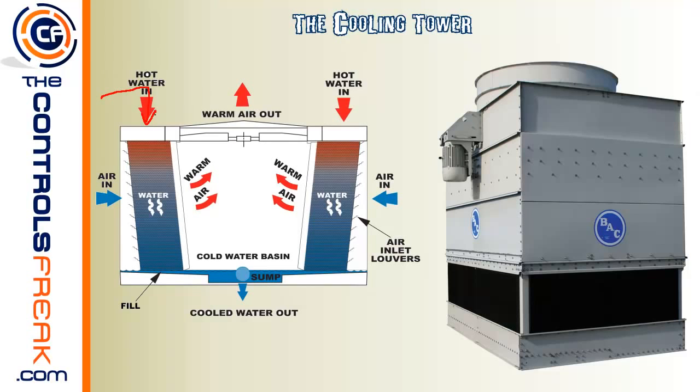And essentially it either has a pipe that just lets the water drip down the side of the tower, or sometimes they have actual little spray heads that actually spray the water and disperse it in a wide spray across the cooling tower. This diagram here kind of represents one where it would just hit this top here and it would just kind of rain down across here.